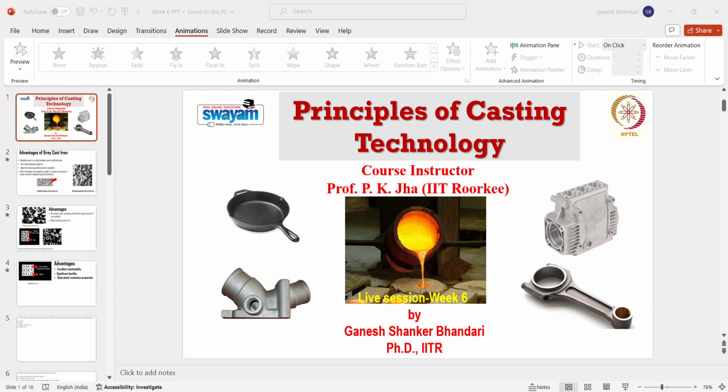These flakes provide the necessary properties to our cast iron, mainly the damping capacity. This type of cast iron has very high damping capacity because these flakes provide the necessary strength for damping applications. Generally you can see this type of cast iron plate used beneath lathe machines, because they have very high shock resistance. So you can use them as the base for heavy machinery.